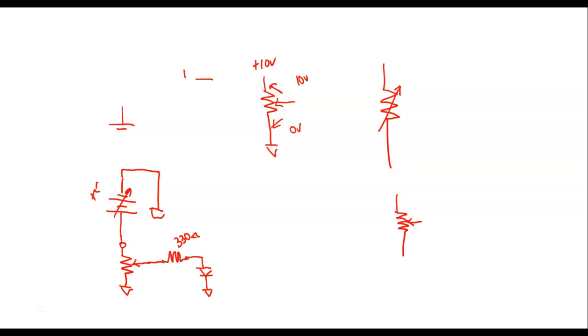So on that transformer, your circuit establishes your common. The way you wire it establishes your common. Now, as soon as you hook that scope probe up, you establish a ground. So that little old black lead on your scope probe is ground. And that's one reason why you can't move the black inside the circuit.